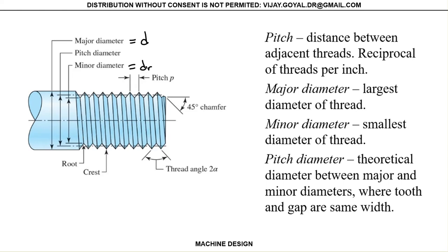We call that the root, which is why it's called DR. Then the pitch diameter is the mean diameter between these two diameters, and sometimes we also call it DP because it's pitch or mean. Many textbooks interchange these back and forth, but it really means the same. The outer diameter is if we just take the full length right here.